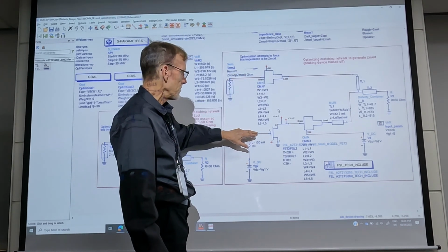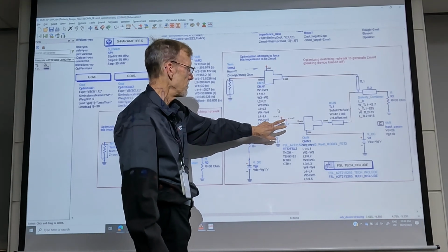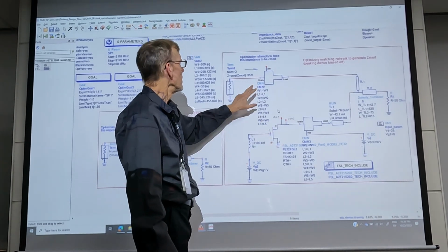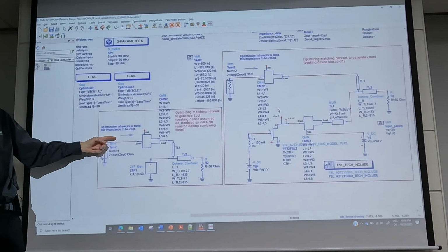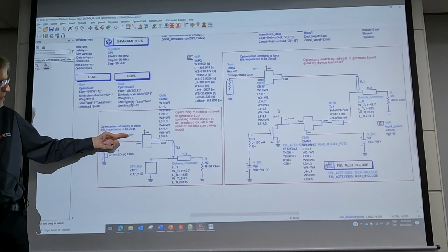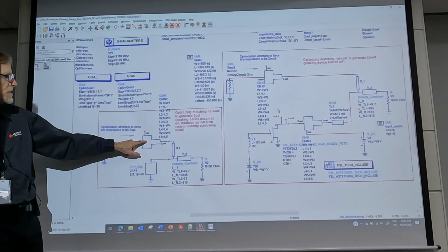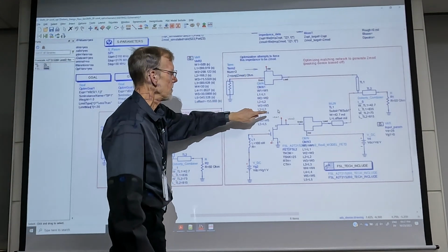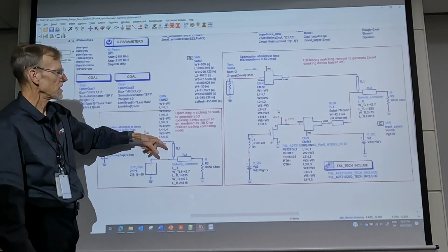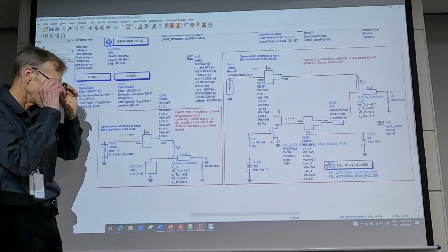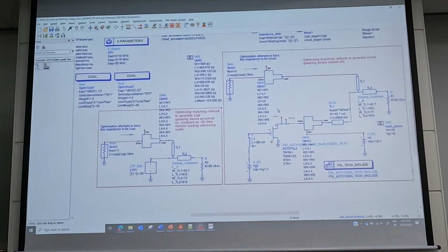That would be with the peaking transistor off. That's Z mod, and then with the peaking transistor on, this is Z opt. Ideally, looking to the right, these two are the same. These two happen to be the same network, so it's the same set of values we're trying to optimize under both loading conditions. Does it make sense? Yeah.